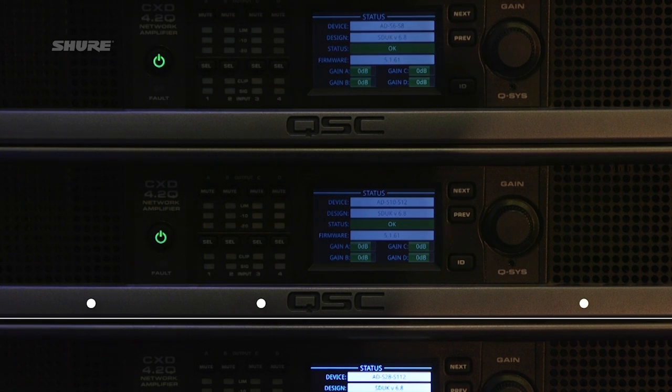The next element in an audio system is processing. Before we reach the processing, we need a way to boost our microphone signals up to a suitable level. This is usually accomplished either through an external microphone preamplifier, or most processors nowadays have preamplification built in. The most basic processing that you'll see is a mixer. All we're doing there is taking our input sources, whether they're mono in the case of microphones or stereo, and mixing those into one or more stereo outputs to feed maybe different zones or feed amplification and loudspeakers within our room.